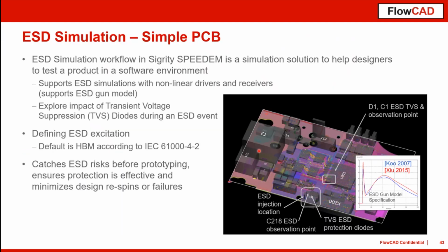So now we come to the end, but just two words about the so-called ESD simulation. In this case, we inject into our design an electrostatic discharge pulse, which is modeled here by a SPICE model ESD gun, you can say. These two different approaches can be used to achieve an ESD pulse, as it is defined here with the IEC standard.